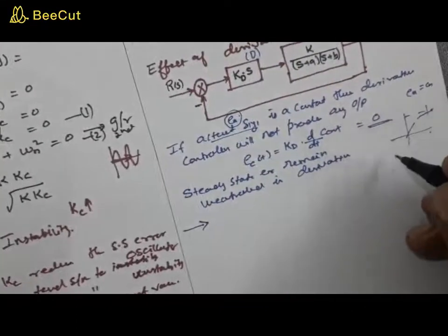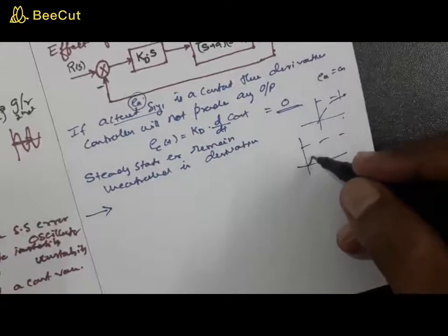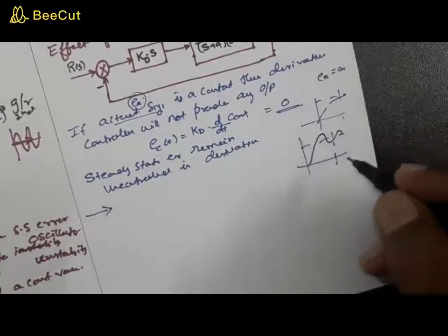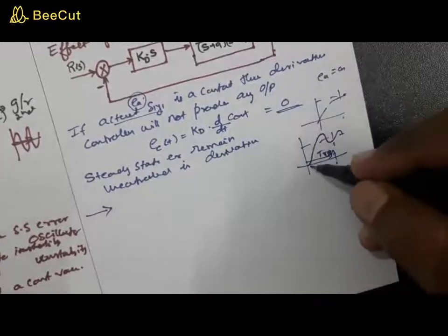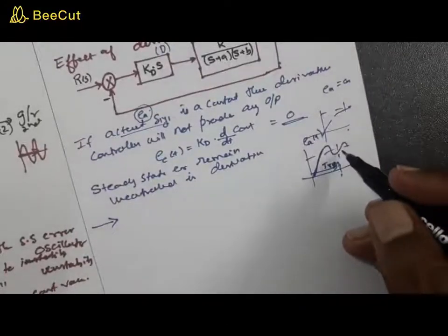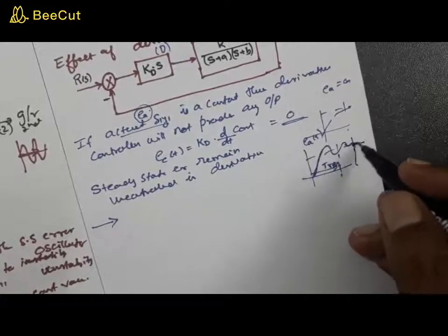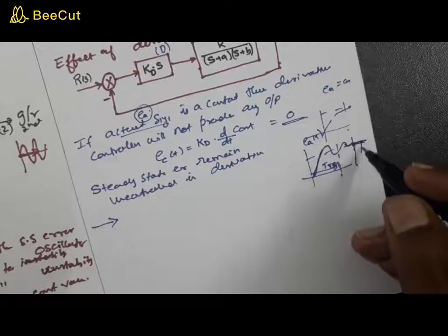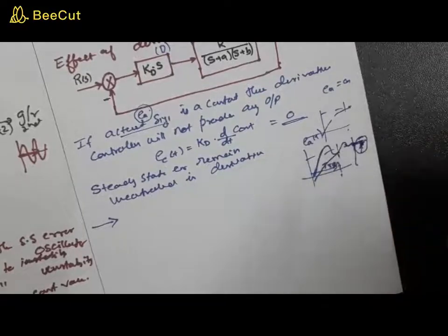So you know that for a second order system, for a step input, you have studied something like this. So this we call the transient response. So what is the specialty of the transient response? During the transient response, this keeps on changing. That is, the e_a(t), or the actuating signal, keeps on changing till it reaches a steady state. Once it reaches the steady state, it almost remains a constant. So the derivative control has the least importance once it reaches the steady state. So it will have importance during the transient state.